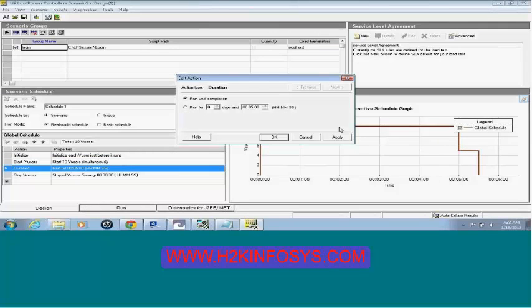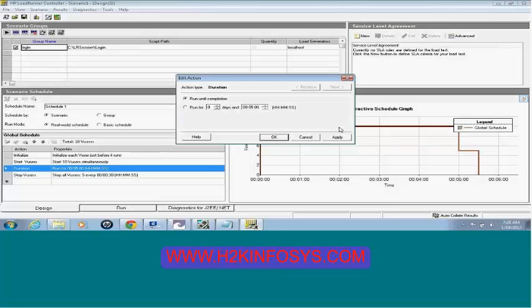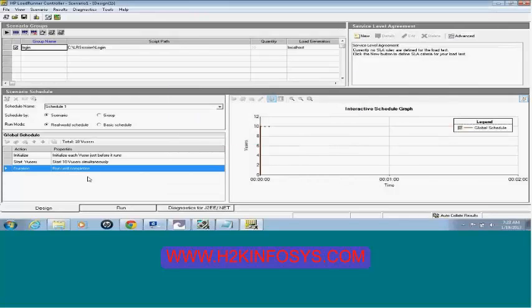Run until completion means all 10 users are going to run, perform their jobs and then complete. So select run until completion and click OK. It gives you a confirmation asking if you want to make these changes. Say yes, and now you're all set with the global schedule.